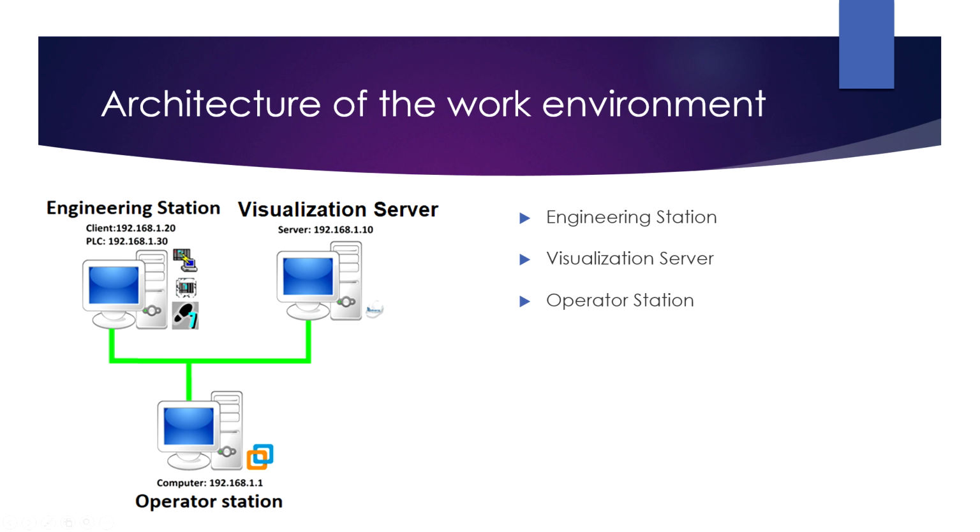It has three key tools installed: Step 7, version 5.7, tool for programming Siemens PLC controllers; PLCSIM, software for simulating the operation of a real PLC controller, allowing testing of programs without needing a physical controller; NetToPLCSim, software that simulates the connection between the PLC controller and the network as if the simulated controller were a real device on the industrial network, enabling communication with the ECS system.